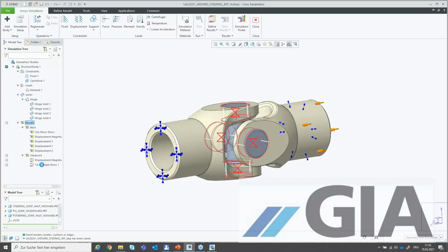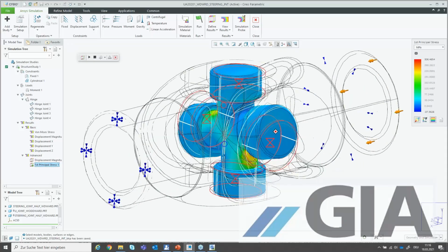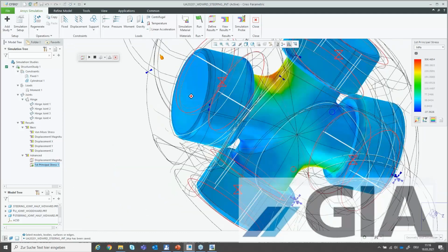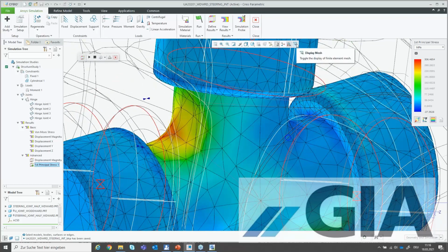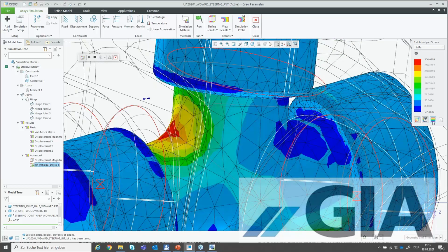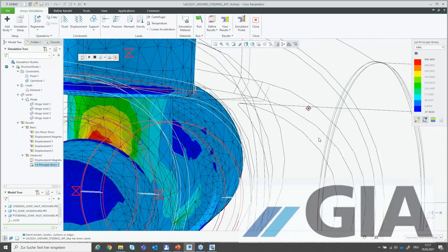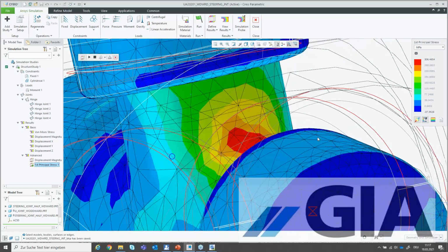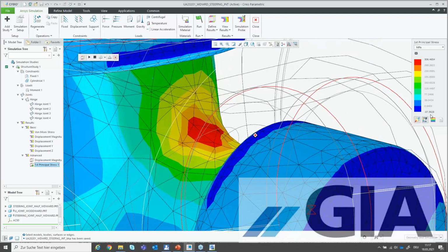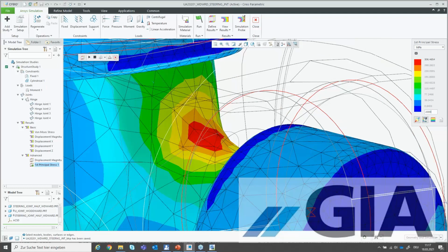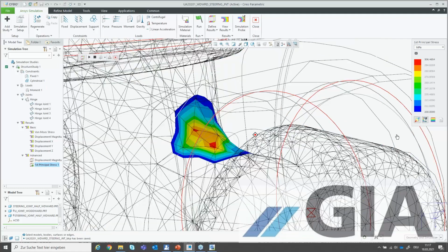Okay, and now by activating these advanced results, I can see the behavior of those components here. Of course, the mesh is also available. And here we can also switch to another mode, and we see, okay, this is too coarse to get any really nice results. We have around 300 megapascals, but when you change that value to 200, then we see this result is really very coarse.